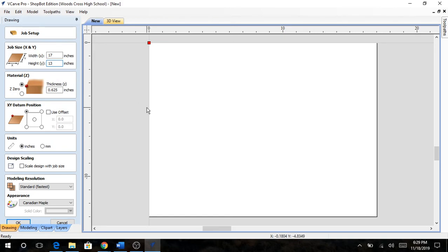Okay. Now keep in mind with all of these, with your lid, you're going to have about a 1/2 inch all the way around where you've done your cove router bit where it won't engrave. So keep your designs in about a 1/2 inch at least, maybe, you know, an inch.